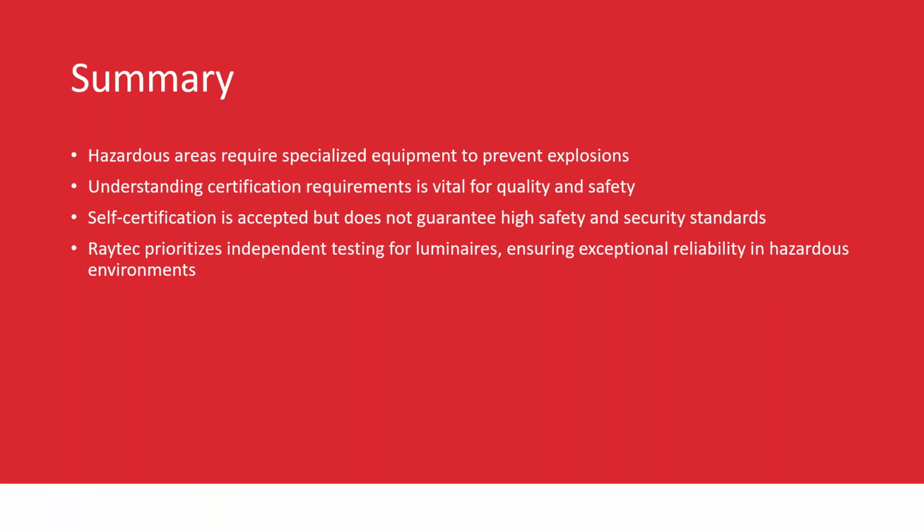The method of protection used during certification, so you are clear how the luminaire has been designed and will need to be maintained. And 4. The type of hazard to identify the risks of ignition and the severity of any potential explosion, allowing the correct selection of equipment for that particular specific hazardous area. So following this general rule of thumb, when specifying your hazardous area equipment, you can generally rest assured that the site is protected to the highest possible standards.